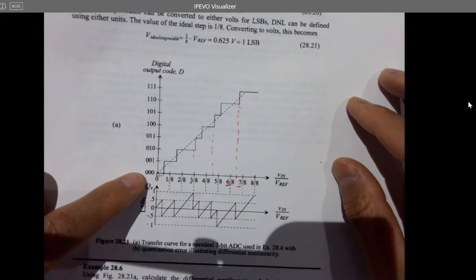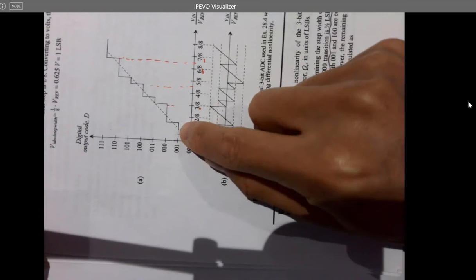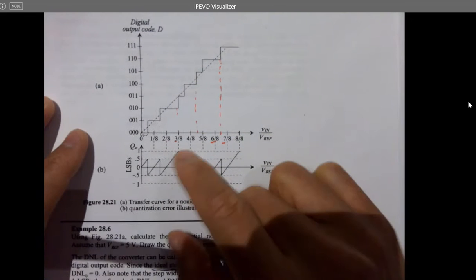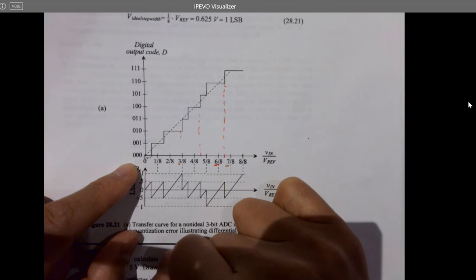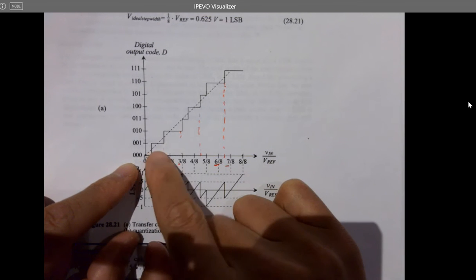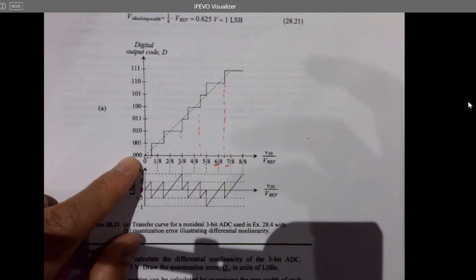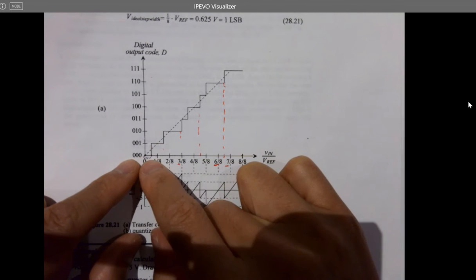So for example, DNL 0, imagine you are rotating this guy. For the ADC, this is the width, but now this becomes the height. Okay, I'll rotate it back. But when you are thinking about it, just think about it this way. Okay, it's easier. So DNL 0 is expected to be half LSB. If we shift it, right? You are not assuming we shifted it, we're still expecting 0. It's not. So we're expecting half LSB.